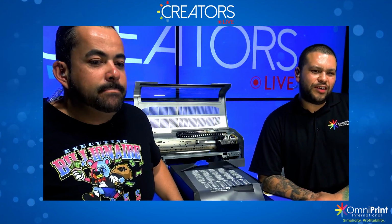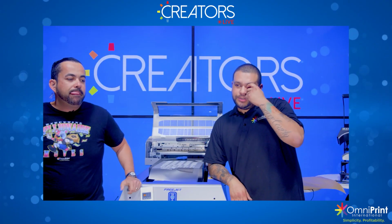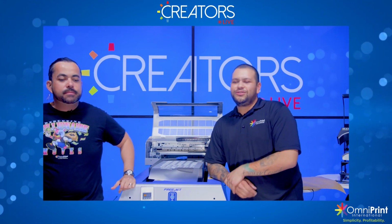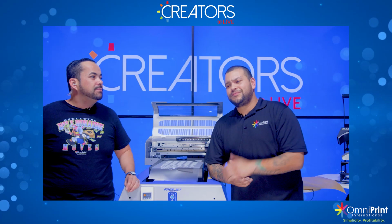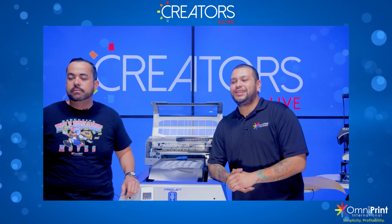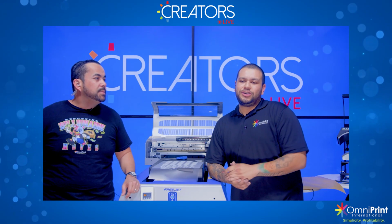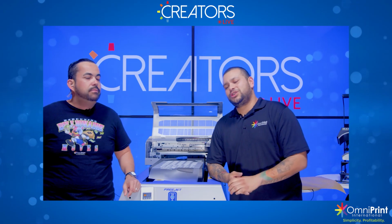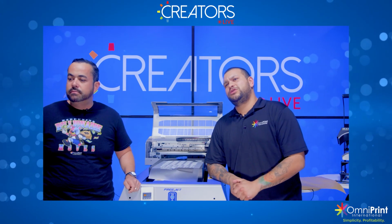Maria said, for more delicate fabrics that burn at higher temp, are we able to lower the temps? Since we're only really cooking it for 15 seconds, you almost don't give it enough time to start burning it up. I've done it on poly and I've done it on cotton. Like I said, I've even done leather. Last week someone brought backpacks into the office, and they wanted to print on backpacks. So test it out. Like I always tell customers, if it's going to burn without even putting the transfer on there, then yeah, we'll have to make some adjustments. But I haven't run into too many fabrics that I've burnt up with those 15 seconds.